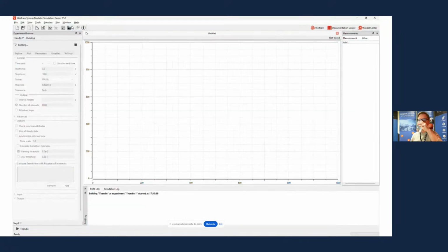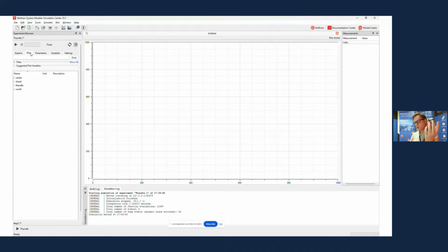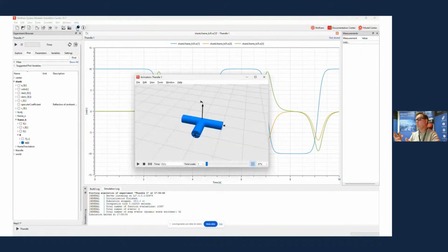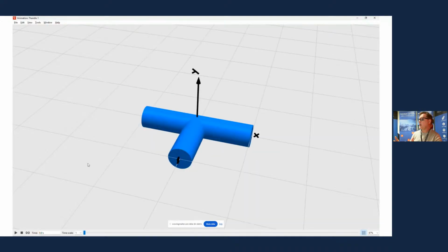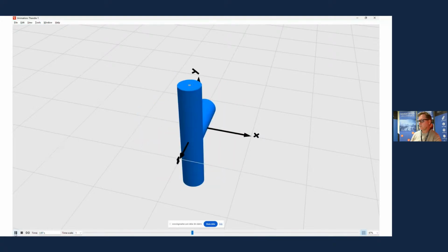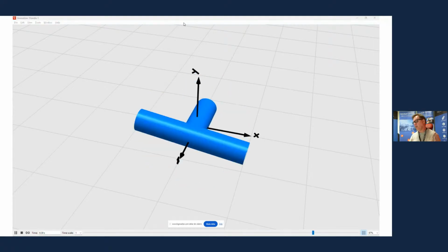And then I simulated. Once simulated, there's plenty of things I could plot, like every single variable in the system is available. But what I chose to plot was the rotational speed of the shank. So I dug down to find it, W here, and we can quickly see, and we'll get back to this, that something is happening, it's flipping. But perhaps easier to see it is if I run the animation. There you go. In just under 4 minutes, actually closer to 3 minutes, I had replicated the Janibekov effect.